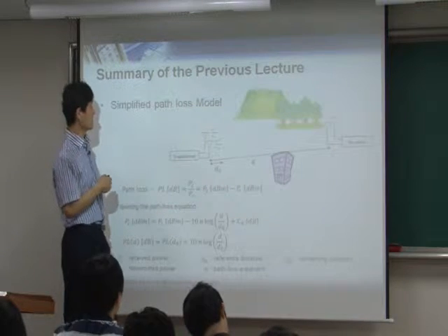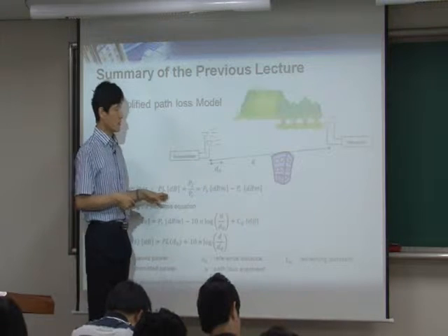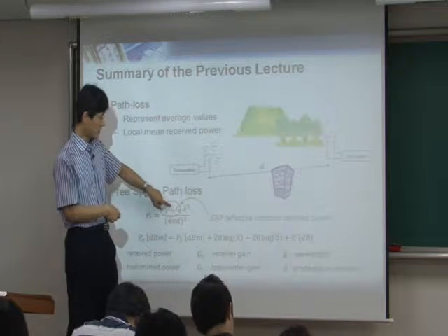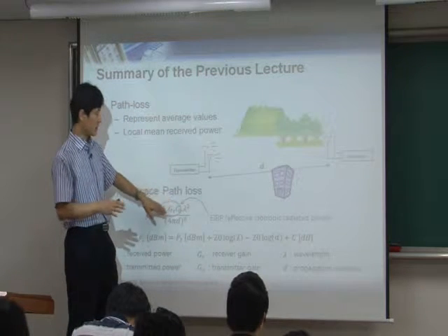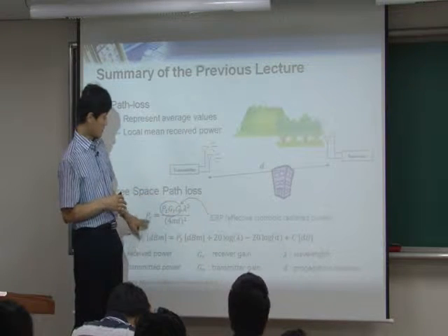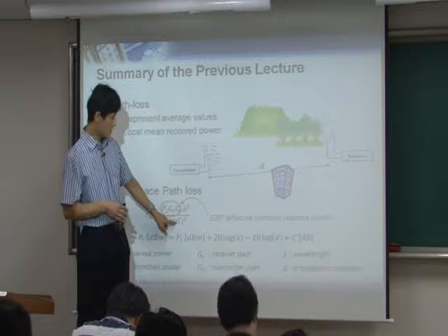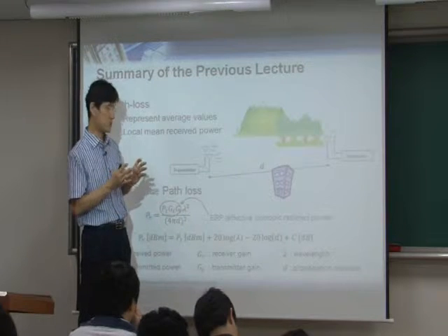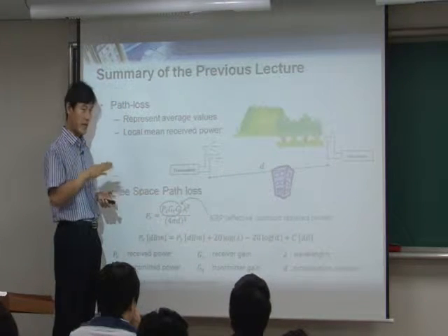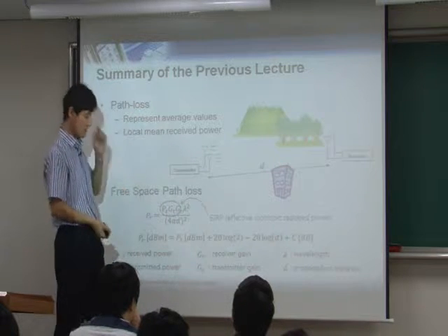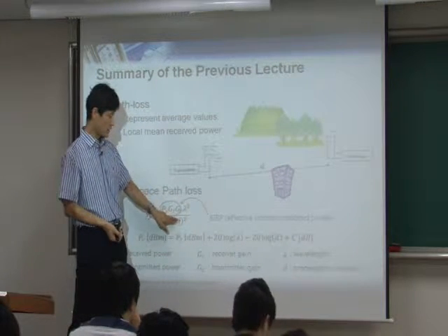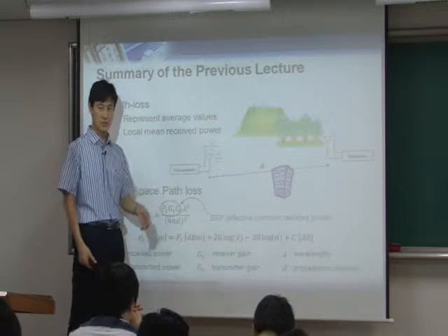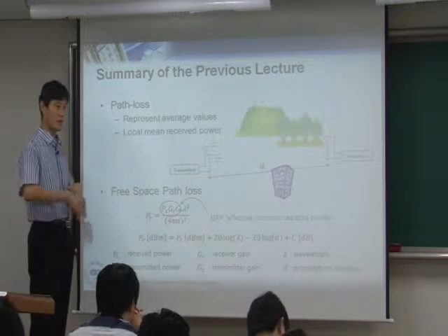You see the simplified path loss model. So here's what's going on. As I said, in free space the previous equation is true, but in an actual environment, this is no longer true. What's happening in an actual environment is that this equation has to be changed such that it's no longer d squared. Your received power is now attenuated at a little bit higher rate. This one is attenuated by d squared, but in an actual environment, it's going to be d to the n. And n, in this case, is higher than 2, right? Could be 3 or could be 4, depending on your environment.